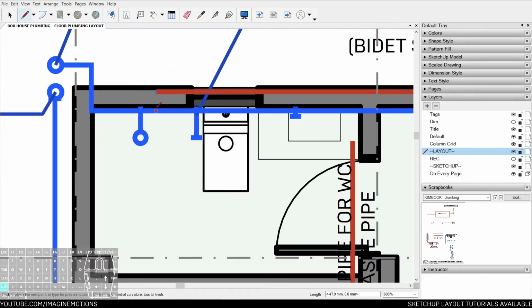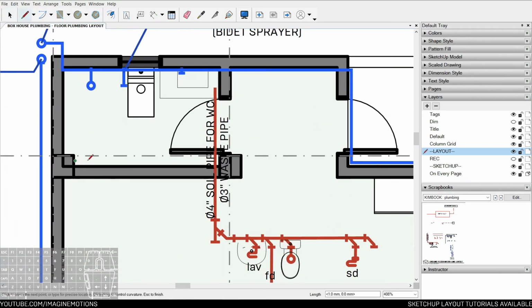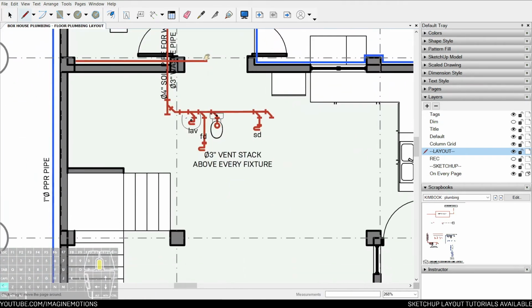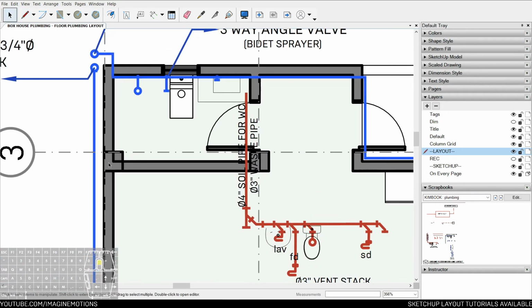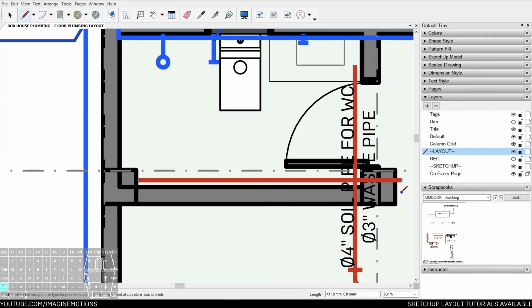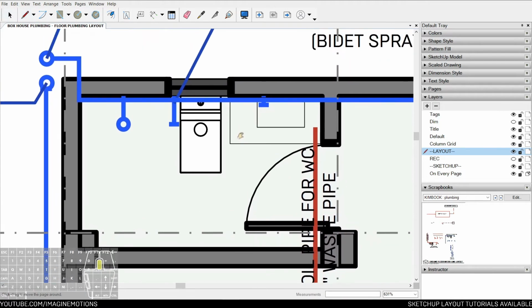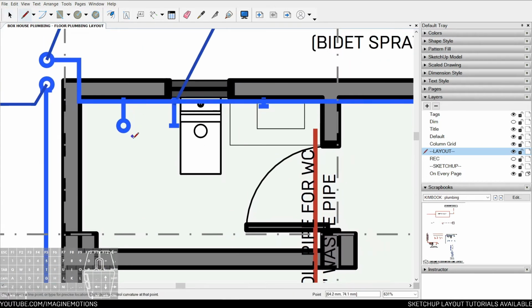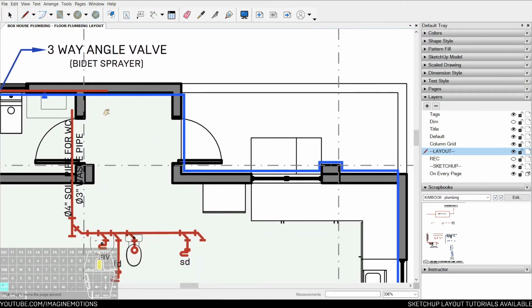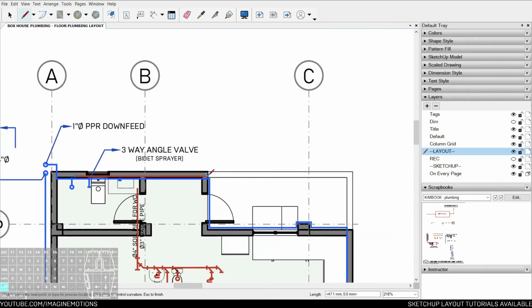But be careful of placing sewer lines where columns are aligned because there is a beam below. So if you choose to put it here, you have to indicate how low or where will be the starting point for the plumber to locate. So let's say I have one line here and I located my septic tank somewhere here at the back.